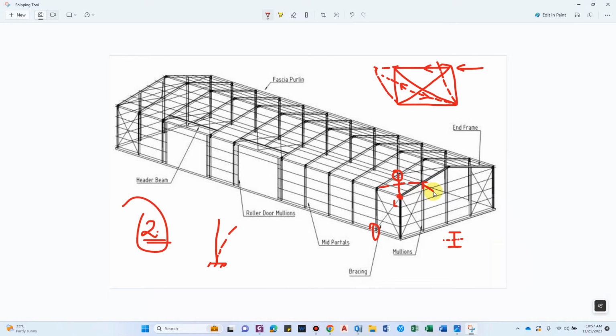So till now, some major points to be considered. One is the direction of the column section for the portal frame action. Secondly, we have to consider the struts for a combined action, that is, for the bending moment due to the upward wind load and axial force due to the lateral wind load.